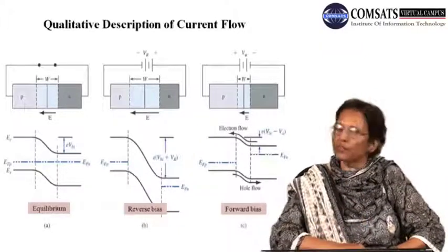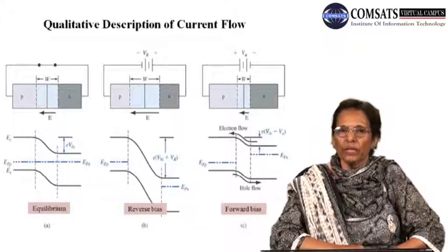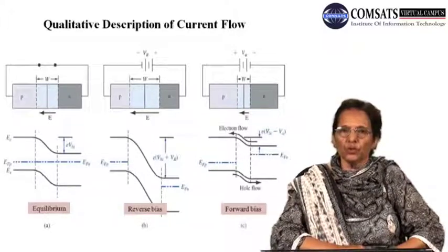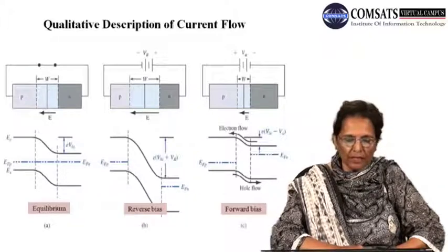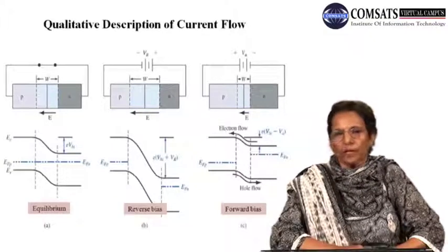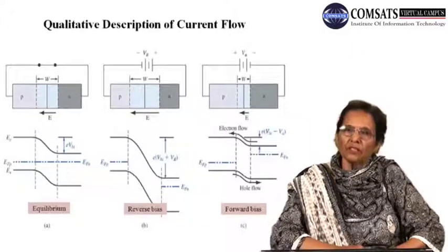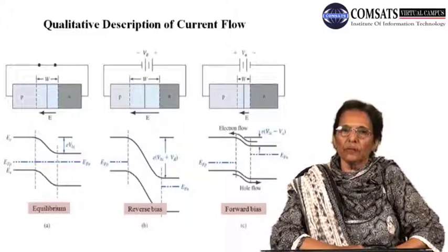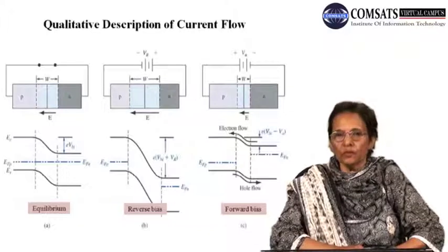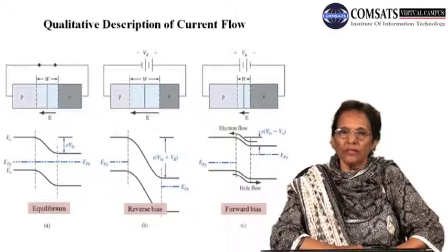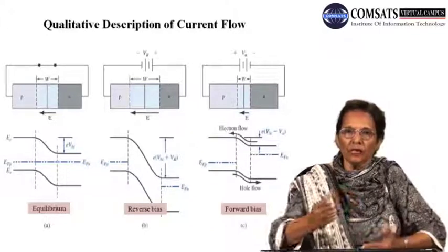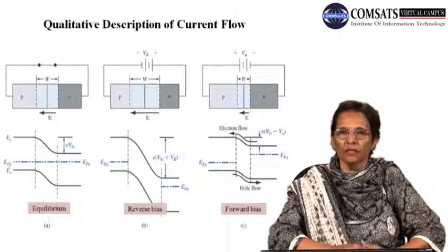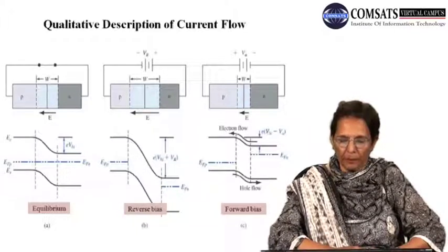In the lower portion of the same transparency, we have tried to show you the variation of the current density and the band bending. The band bends due to the fact that now there is a built-in potential within the depletion region, and if electrons from the n side further want to diffuse to the p side region, they will have to do so against the direction of the electric field, which has been shown on top of the slide, and hence there would be a band bending.